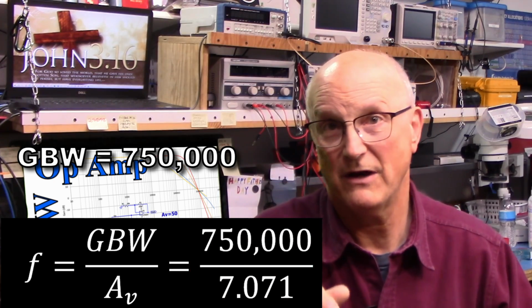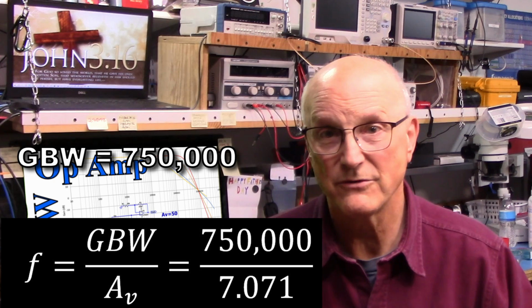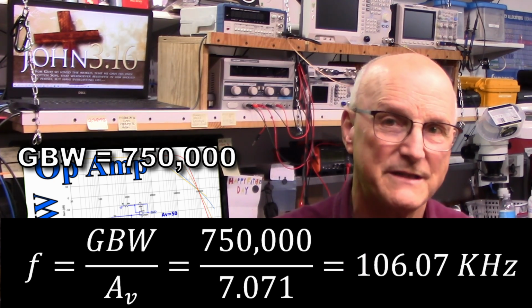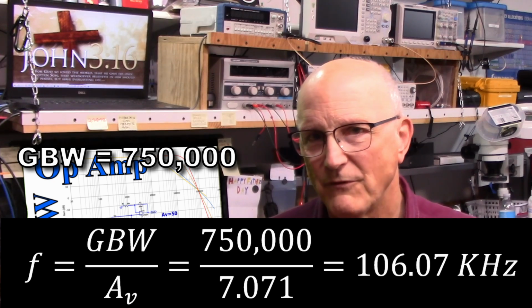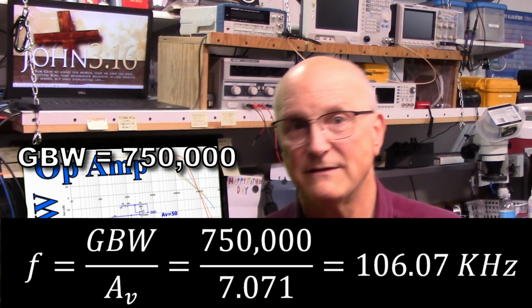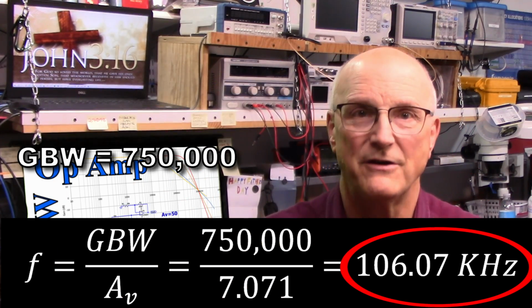So frequency is going to equal the gain bandwidth product divided by the desired gain. So that would be 750,000 divided by 7.071, and that comes out to be 106.07 kilohertz. The gain of each of these amplifiers will not be affected by the gain bandwidth product until we reach an operating frequency of 106 kilohertz. So let's simulate this and see if I'm right.